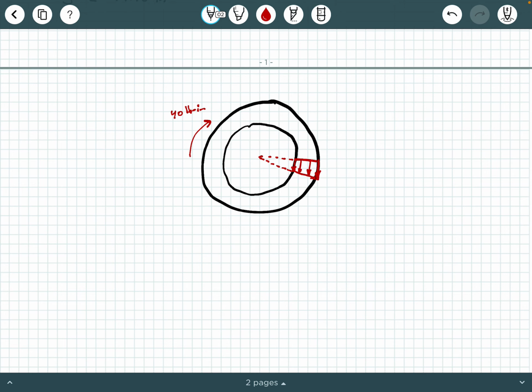Okay, now remember, the shear stress distribution is linear increasing from the center of the shaft, okay? So it starts at 0 and then it linearly increases. Now, you may be wondering, where's my little vector arrows for the middle portion of the shaft? Well, remember, this is hollow. There's nothing here. If there's nothing in this middle part, then it cannot sustain any stress.